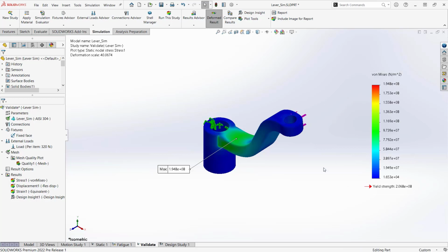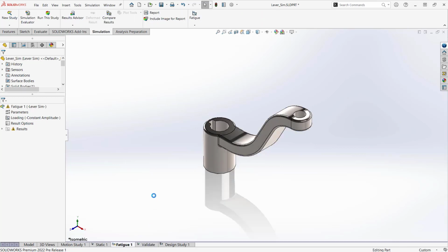However, we've only analysed this for one loading cycle. As we mentioned, this pillar drill is going to get used time and time again. This little crank handle, it's going to be adjusted multiple times. So how do I know it's going to withstand its expected life? Well, that's nice and simple through the use of what we call a fatigue study.